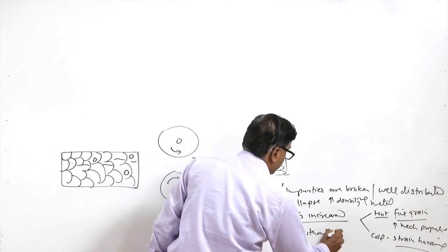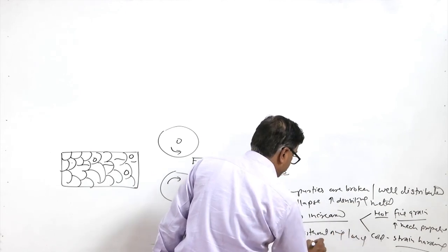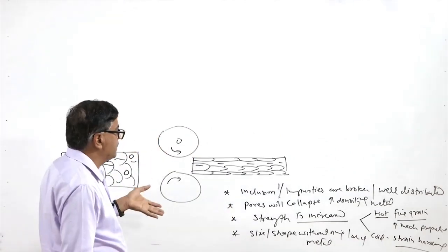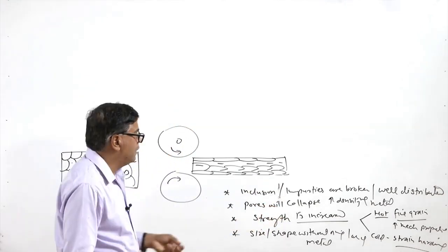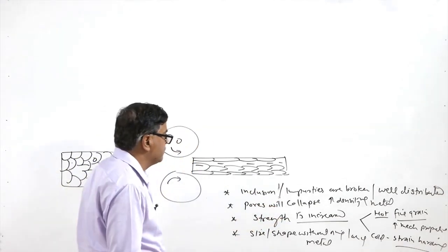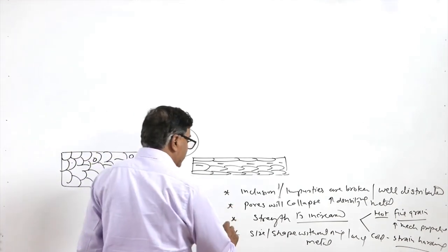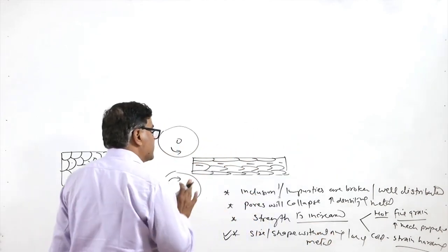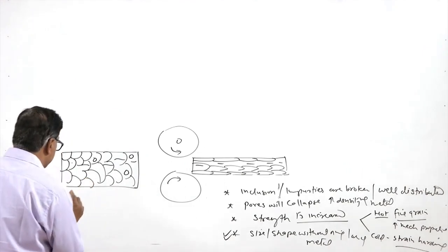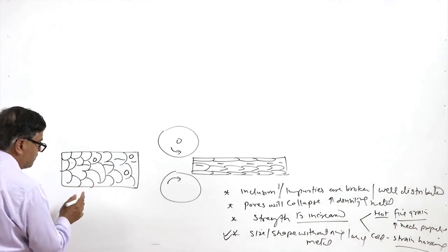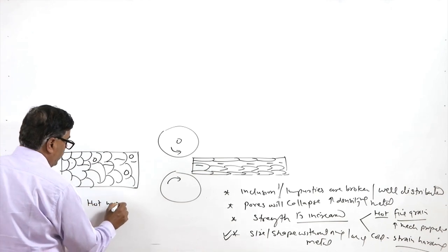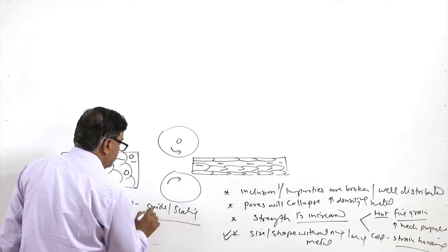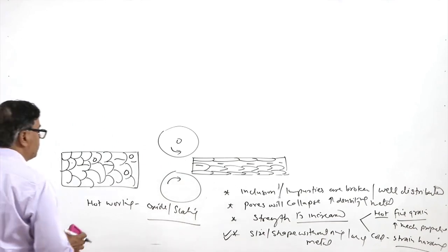without any loss of the metal, because in this case mostly the shifting of the metal from one region to another takes place, and actually there is no loss of the metal during the processing using the deformation based processes. So, the metal efficiency of the process in terms of the metal consumption is very good, because the losses are extremely less, especially little bit losses may occur in case of the hot working based processes, where oxidation and scaling of the metal will be taking place at the high temperature, and which may get